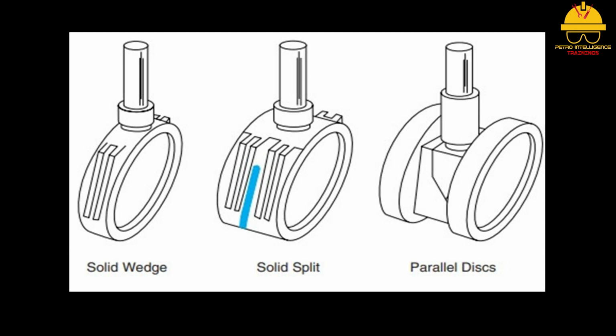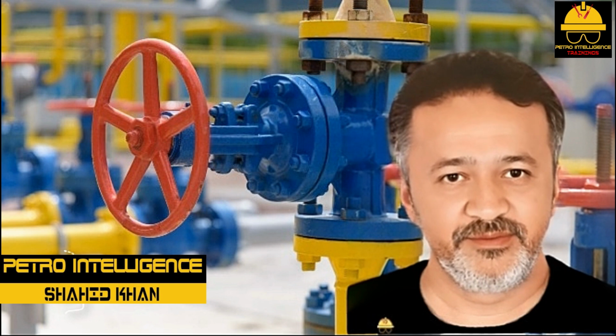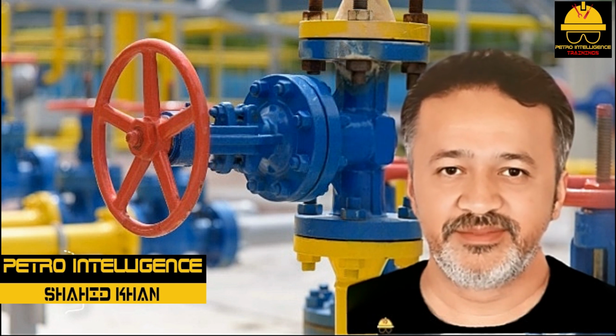As fluid enters this type of valve, it pushes against one of the discs, compressing the spring or flow control element and forcing the opposite disc snugly into its seat. System pressure helps position the gate in its seat. The higher the pressure, the more tightly the disc fits into the seat.